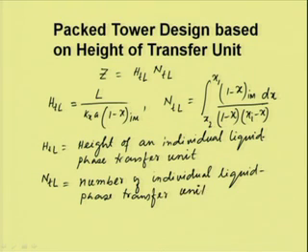So, this is in terms of the liquid phase concentration of the species, we can define the height of transfer unit and number of transfer unit, and then we can calculate the packing height.